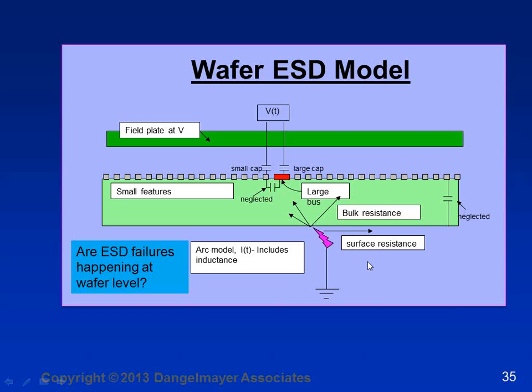You know, you have great care to avoid physical damage to the active side. So therefore, the discharges typically occur to the edges and backside. For this evaluation, the assumption was that the stress would come from the backside. And by the way, it's very common in wafer fabrication to have 5,000 volt strikes or discharges to the backside of the wafer.